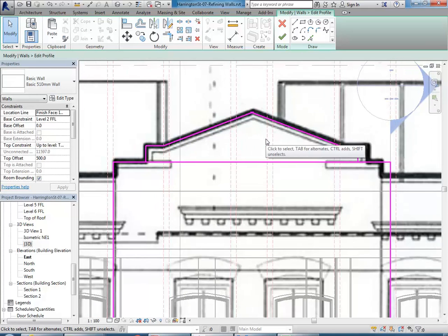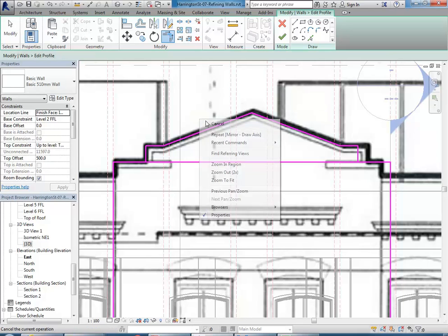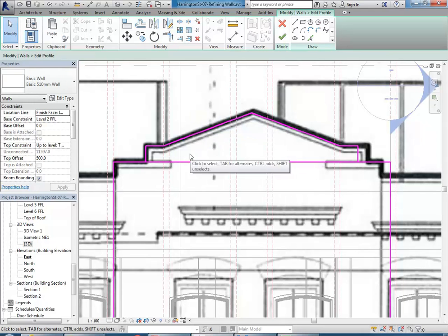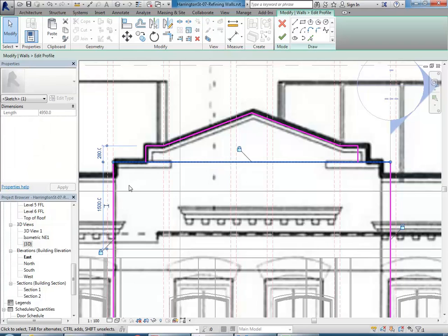And it's a really flexible tool. You're still just drawing in 2D, and it's going to translate all of this into the 3D finished wall shape. One little tip that I can give you there is to make sure you know what are the original edges of your wall. So this here on the side is the original left-hand side, on the right is the original right-hand side, and then this line at the top is the original top edge of the wall. And they're all locked. So if you unlock them or delete them, then you lose the ability to edit them using the original wall. That makes sense?